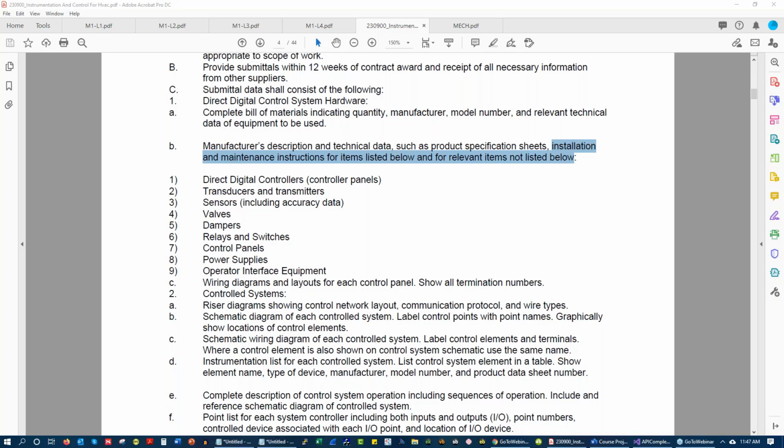In design build projects, with only design intent, what is the best practice for creating documents and submittals? Using templates. You should have templates that cover the basic stuff, so basic rooftop templates, basic air handler templates. There's only so many ways to control an air-cooled chiller, a water-cooled chiller, a rooftop unit, or an air handler. So you should be building out a template library and you can piece those together real quick. So that's a good question.